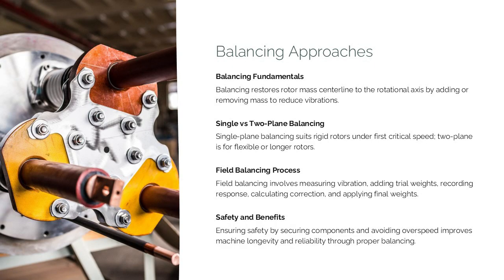Balancing involves adding or removing mass to restore the rotor's mass centerline to the rotational axis. Single-plane balancing is used for rigid rotors operating below their first critical speed, while two-plane balancing is required for longer or flexible rotors. Field balancing follows a structured process: measure baseline vibration, add trial weight, record response, calculate correction vector, and apply final weight. Engineers must ensure safety throughout the process by securing components, verifying trial weight integrity, and avoiding overspeeding. Proper balancing significantly enhances machine longevity and reliability.